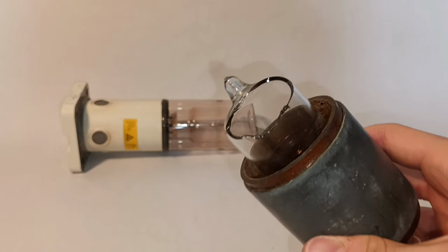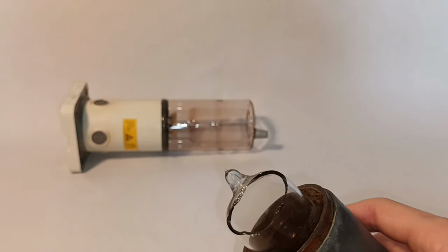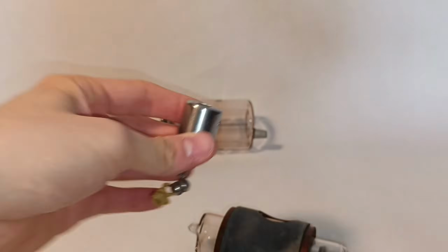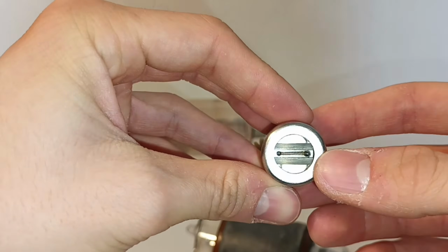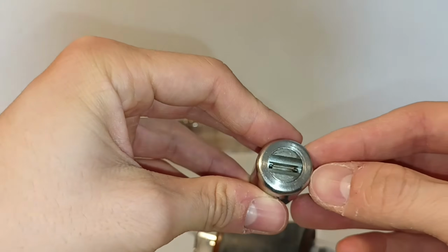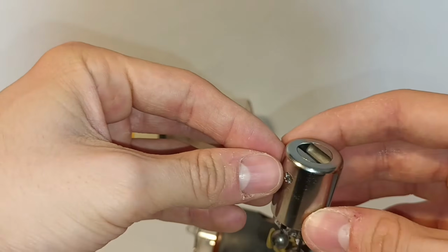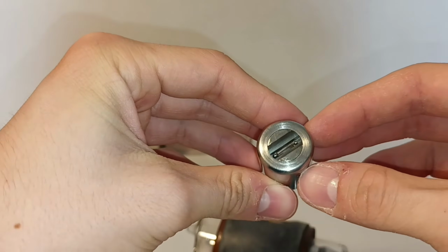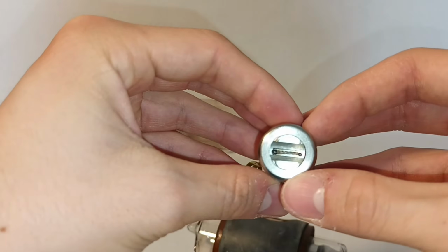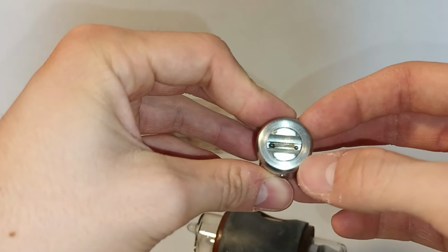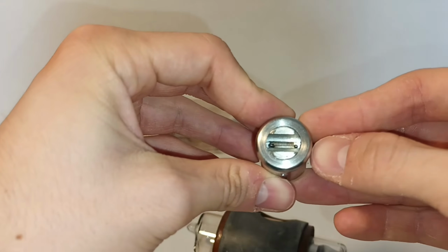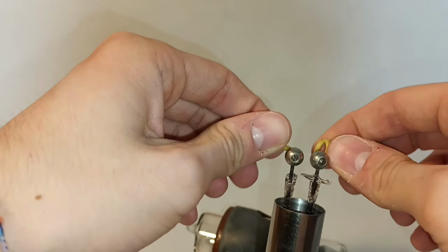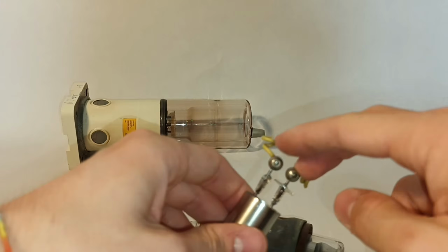As you can see, this tube is broken, and I also have the other part that goes into here. That part is the one which creates the electrons. This is the filament, an important part of the tube that is responsible for generating electrons that have to be accelerated by the high voltage potential and strike the anode. It consists of a simple filament like the tungsten wire bulb that you may still have in your house. It has two electrodes. It doesn't have any polarity because you can run this on DC or AC.